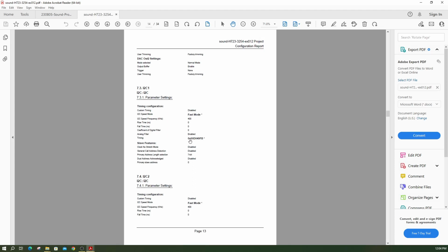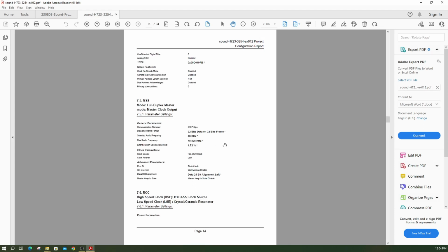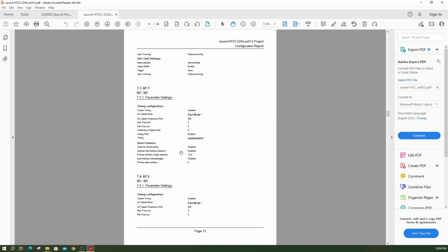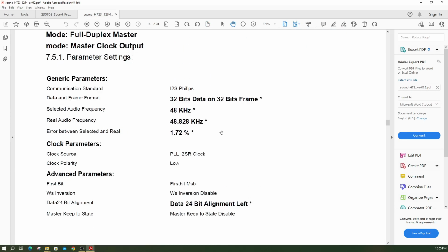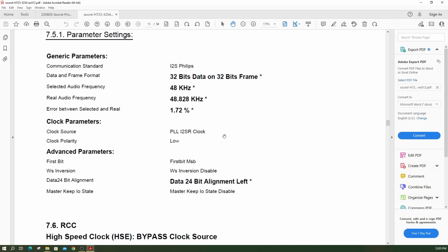And this is one of the I2C interfaces. And the other I2C interface. One's used for the LCD display, and the other one's used for the audio codec. And this is the I2S interface. So we're actually running it at 48 kilohertz, which is the standard I2S Philips standard. And maybe I'll zoom into the I2S interface a little bit. We're actually running it much faster, but we're only really reading it at 20,000 hertz. So it could run faster. As long as that's faster than what we use it at, that's good.